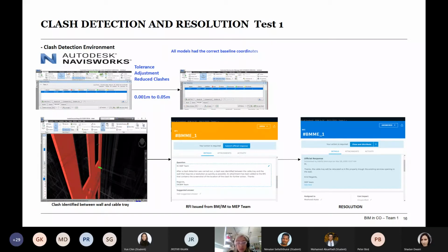The clash detection, we talked about this last week, and you were meant to be doing a clash detection simulation in your project so you can demonstrate and actually talk about this in your presentation. So the idea of moving to a site with 0 errors, 0 clashes, and a reduced number of RFIs and changes is an ideal situation to be in, and saying in your presentation how you would manage that will be useful.